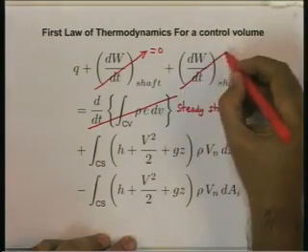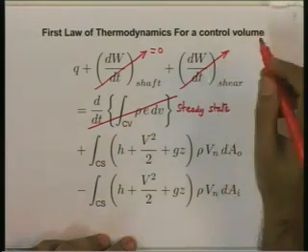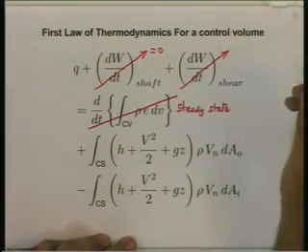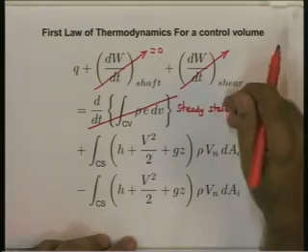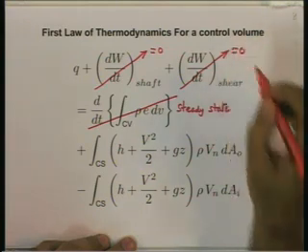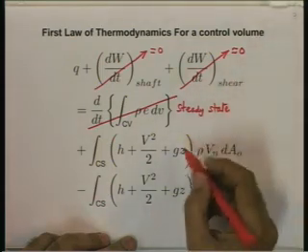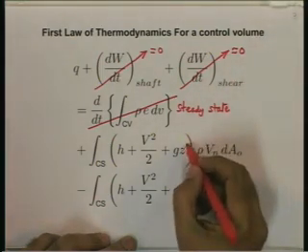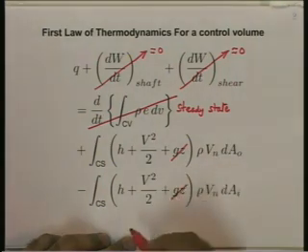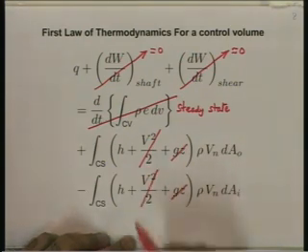We will also neglect shear work. In a large number of heat transfer situations, the shear work term doesn't exist. It's absolutely negligible. It becomes significant only in case of very high speed gas flows, high Mach number, almost hypersonic flows. So this also is negligible. Then we will also assume that the potential energy terms and the kinetic energy terms are negligible.